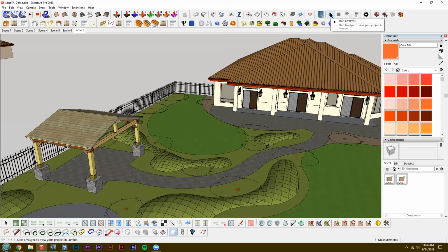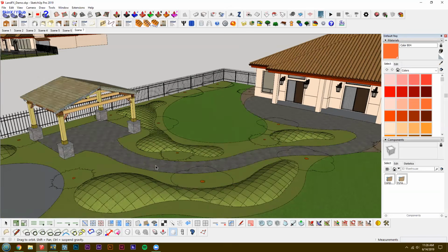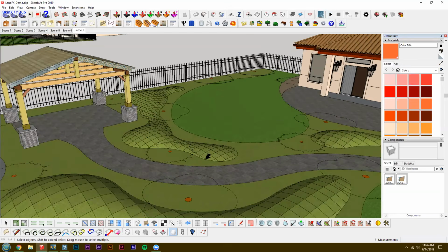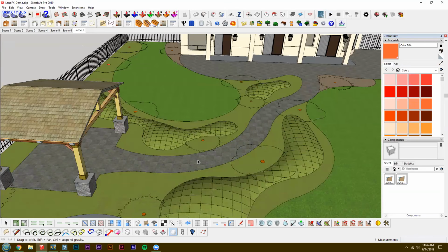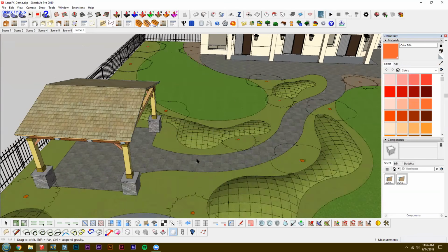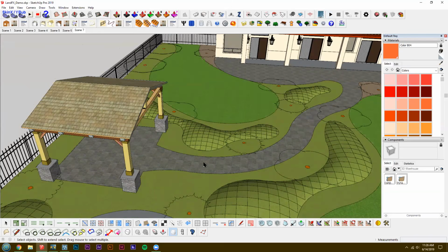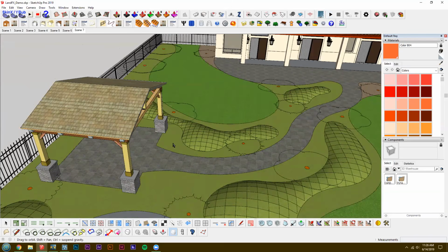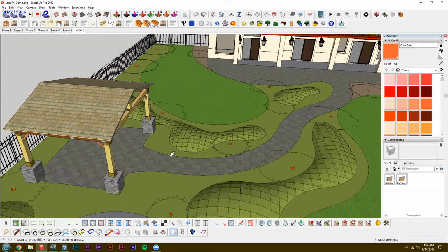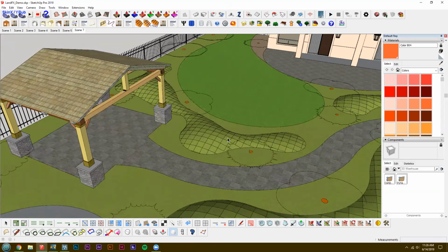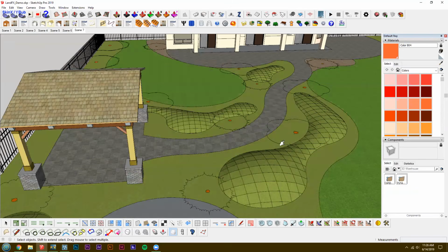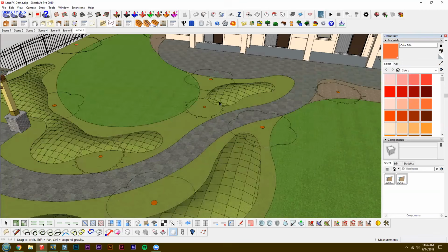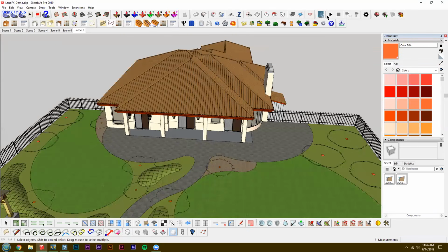But you can actually link SketchUp and Lumion, and so anything you do will immediately show in Lumion. That's good for placing things. If you have houses in Lumion and you need to put the driveways in front of the garage, but you don't want to bring the houses into SketchUp, then we'll use the Lumion extension. And you can also move things around and get them exact with that plugin.